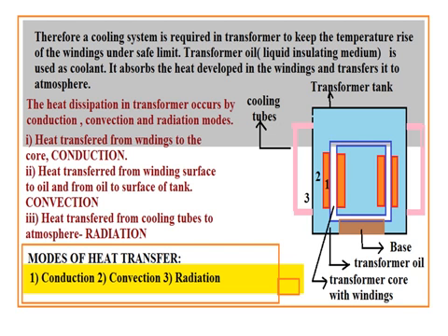Number 3. The heat then goes from transformer oil to the surface of walls of tank and then cooling tubes. This hot oil goes to the top, hence circulates in cooling tubes. The hot oil coming through the cooling tubes is surrounded by the atmospheric condition. Natural air absorbs the heat. In this manner, radiation process also takes place. So, as shown in figure 1, 2, 3, conduction, convection, radiation process. So, this is how the heating process takes place in transformer.